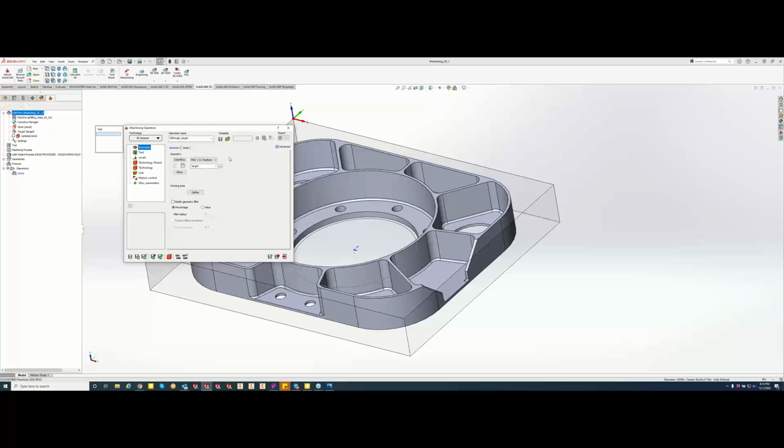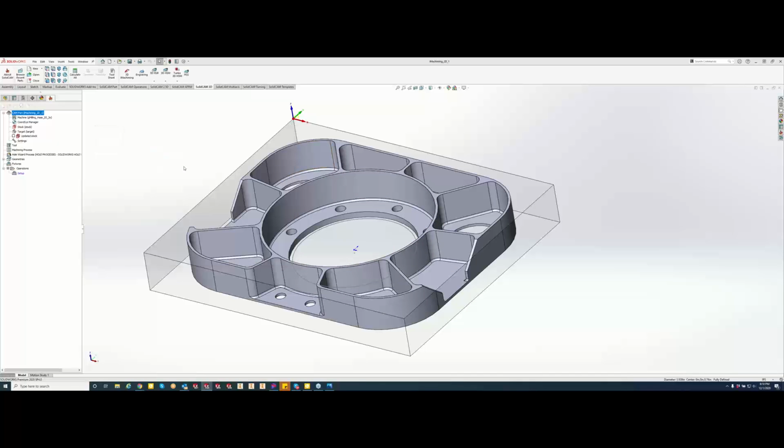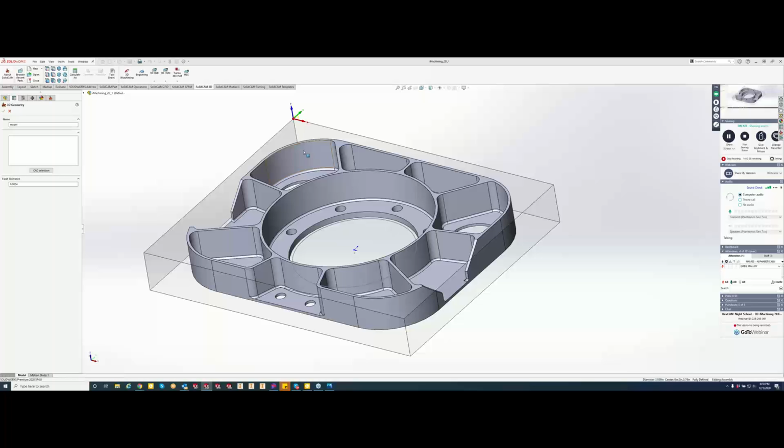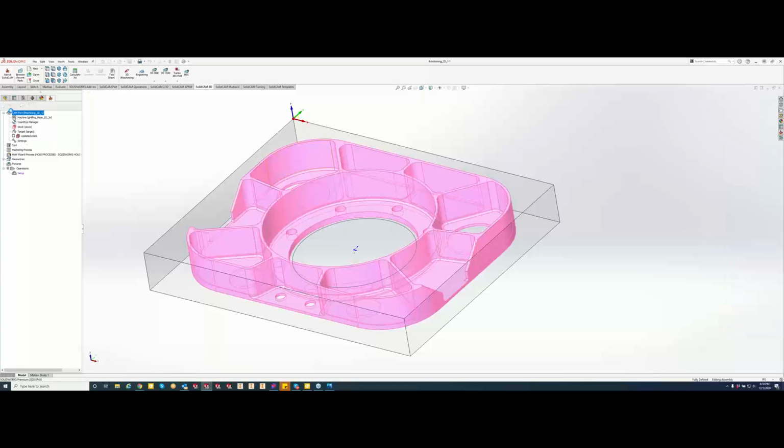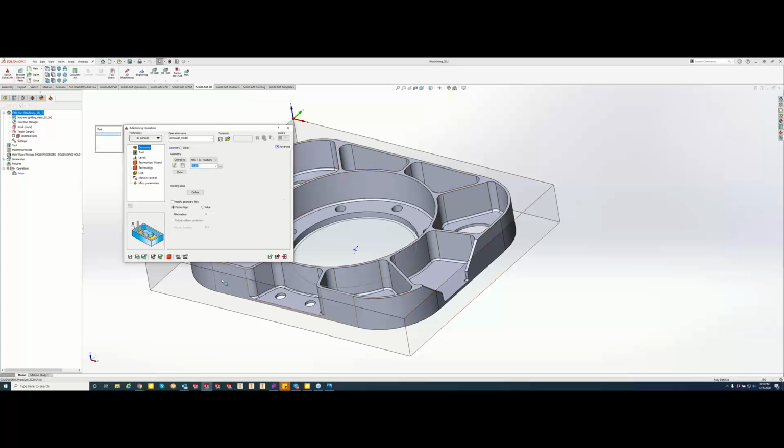So starting at the top, what do we want to cut? We are looking at cutting the target. If you have multiple targets and you just want to focus on one area, you can do the new option right here, and we can select right on our model. You can contain it, as well as a working area. So maybe we just want to focus on a specific area. We can tell it we just want to work contained into this area, doing an internal, external, tangent, and center right there for you. So you can create your own bounding box.